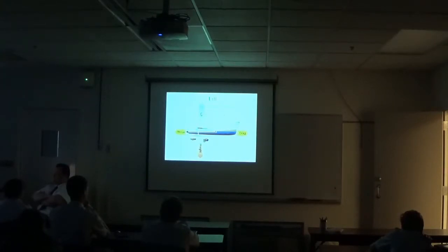At an altitude of 18,000 feet, the density of the air is 1/2 the density of air at sea level. In order to maintain its lift at a higher altitude, an aircraft must fly at a greater true airspeed for any given angle of attack. Warm air is less dense than cool air, and moist air is less dense than dry air.